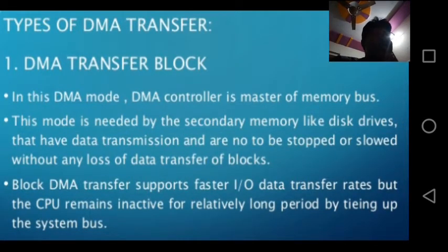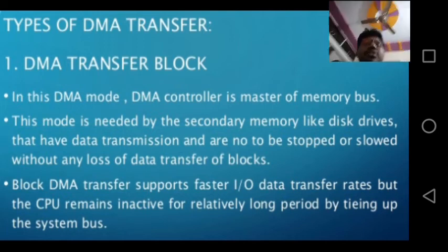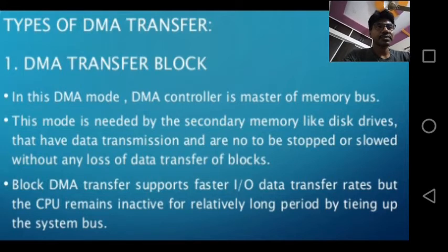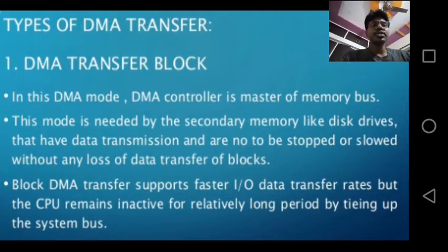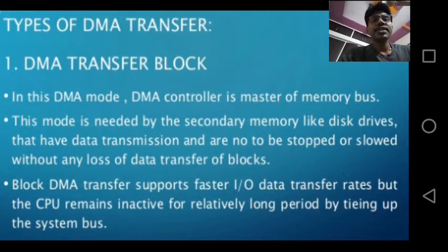So we'll see the types of data transfer. One is DMA transfer block. In this DMA mode, the DMA controller is the master of the memory bus. This mode is needed by secondary memory like disk drives, whose data transmission is not to be stopped or slowed without any loss of data.